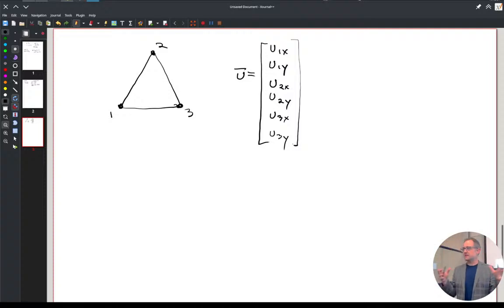And my stiffness matrix is going to describe how much force it takes to move any of those in any direction. Taking number 1 and pushing it right towards 2 and 3 and keeping them the same has a stiffness associated with it that's different than taking all 3 and rotating them. That takes no force to rotate because we're not considering momentum.